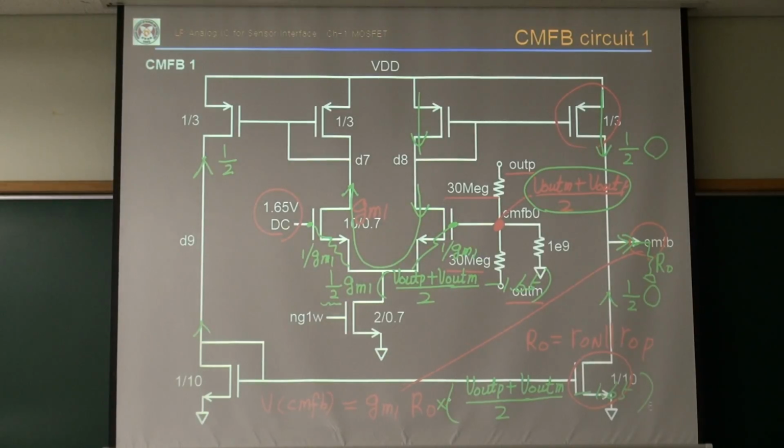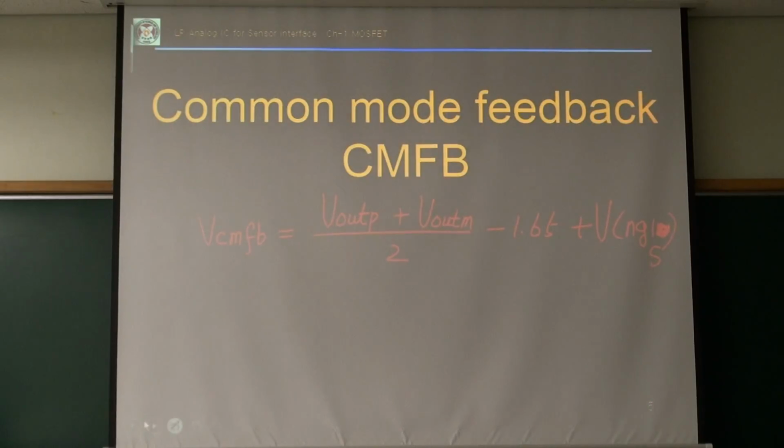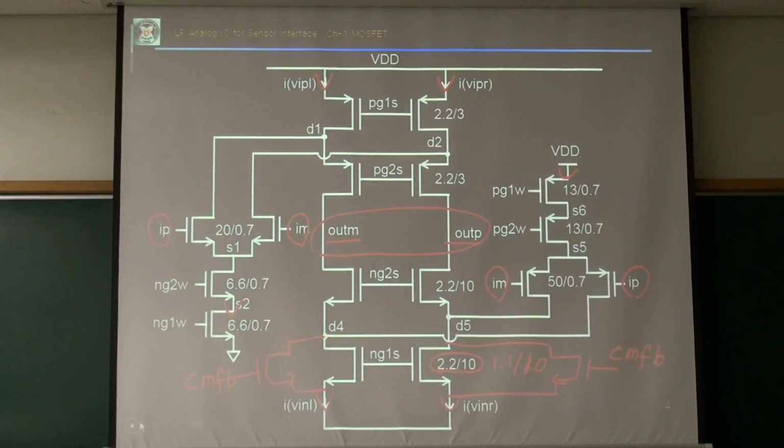Something like that. So the gain should be positive, right? It flows into RO. The gain is positive. Then this one will make a negative feedback for the common mode circuit. So here, if I apply that CMFB output from gate to drain, it is a negative gain. Source to drain, the positive gain. So it is a negative feedback circuit.